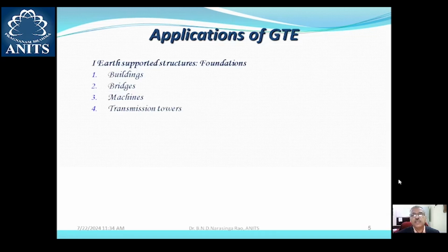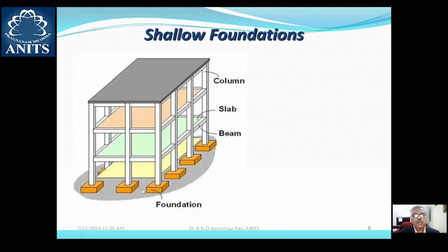You probably are aware that one of the important applications of geotechnical engineering is the design and construction of safe and economical foundations for structures, which are referred to as earth supported structures, in the form of buildings, bridges, machines and transmission towers, etc. If the foundation has a depth which is less than or equal to the width of the foundation, it is referred to as a shallow foundation.